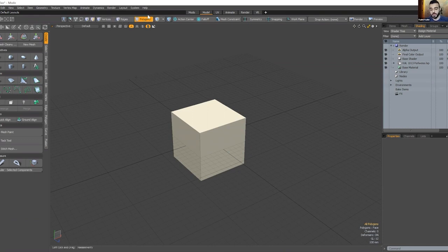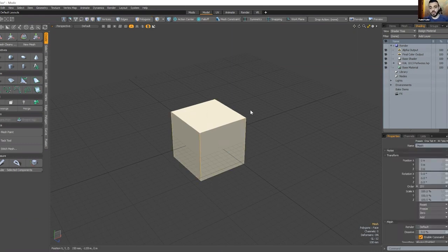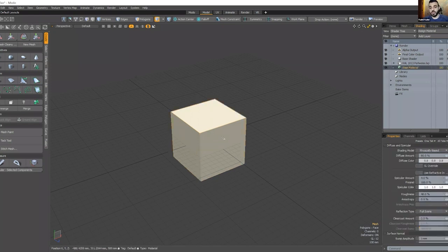Or you can refer to your keyboard and use the numbers. Number 5 is typically where you control the primitive geometry itself. Number 4 is when you control the material. And number 3 is where you control the different polygons, and I'm simply clicking on them. Number 2 is for the edges. You're basically switching between the modes. So when you press number 2, you can never select the polygons themselves. And then number 1 is where you can control the vertices.